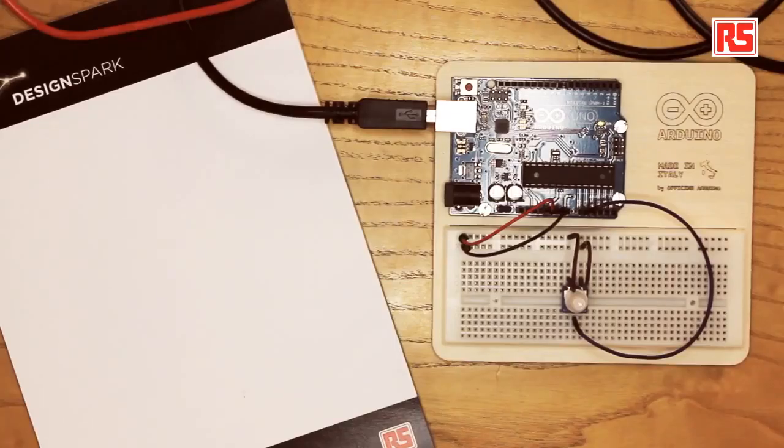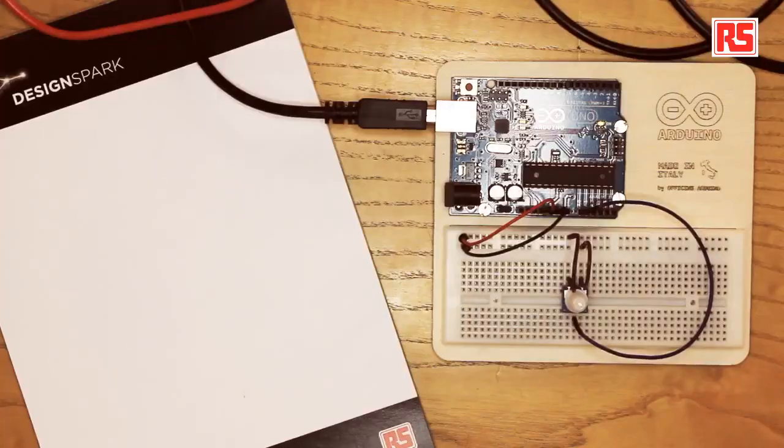There is a button on the Arduino IDE called Serial Monitor. If you press that, a small window opens up, and you can see all the data that comes from the Arduino board scrolling down the small window. There is a little menu at the bottom that normally says 9600, and that's the speed of communication used by the Arduino to send the data. So the Arduino's speed of sending and the Arduino IDE's speed of receiving have to be the same in order to keep the data readable.